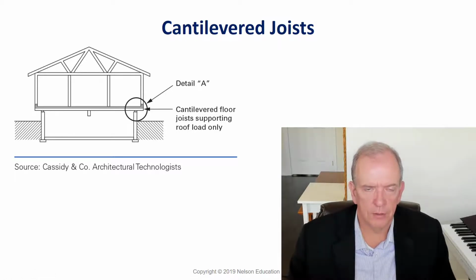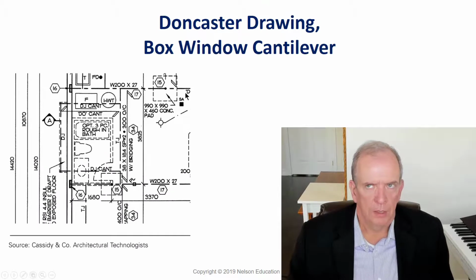And don't take me for granted on the 2 feet. I'd have to double check that, but I guess 2x10s, 2 feet, 2x8, 16 inches, but I have to double check.